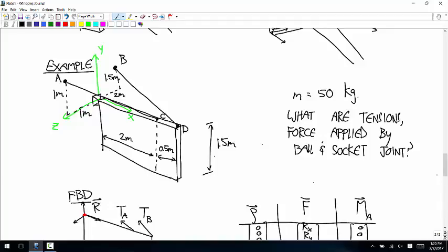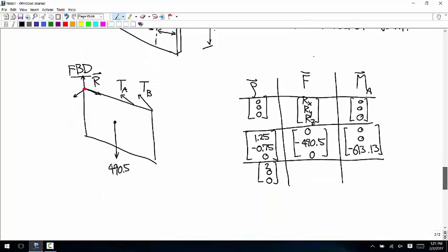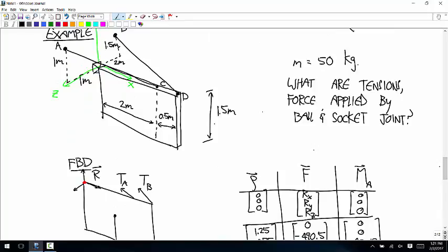So you get a vector that's pointing in that direction, and then just take a unit vector, divided by its length to get a unit vector in that direction. Okay, so we can think of what the coordinates of A are, what the coordinates of C are, and then a vector going in the direction of this force TA is A minus C.